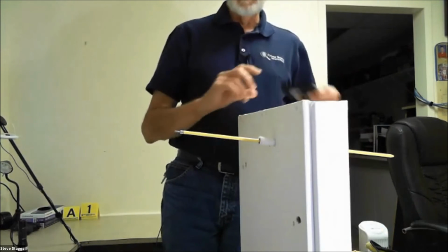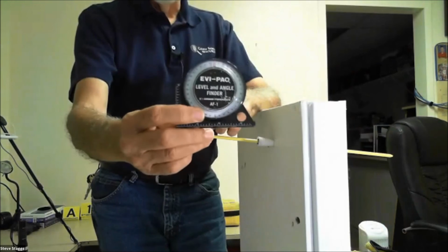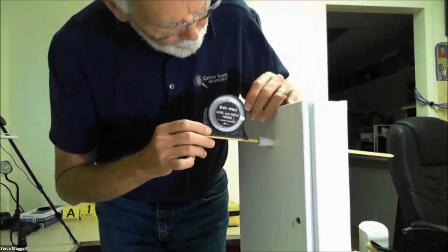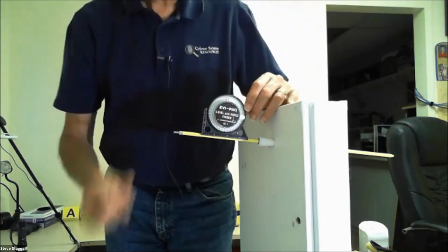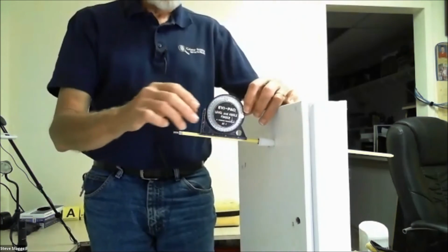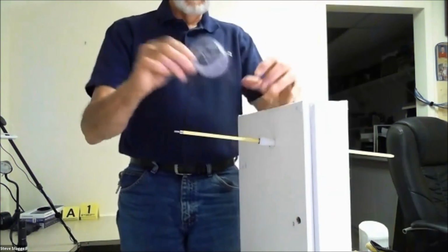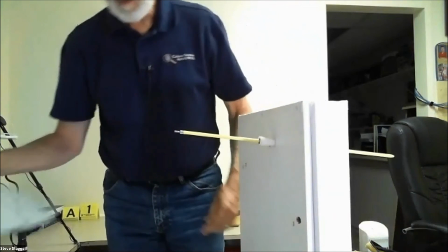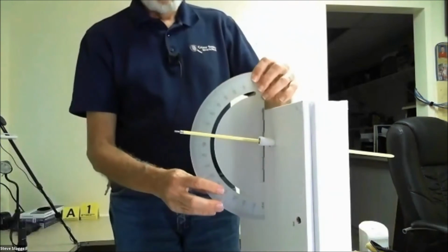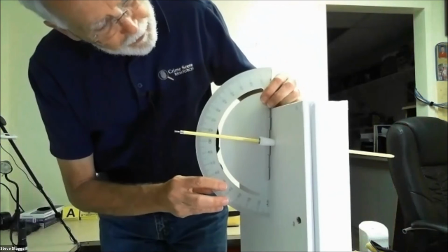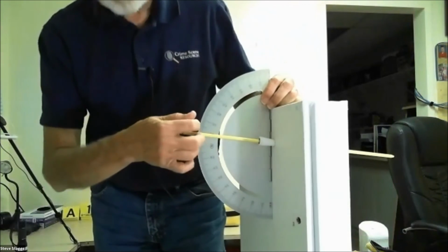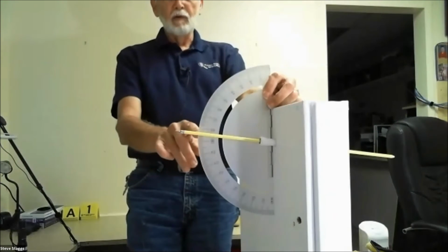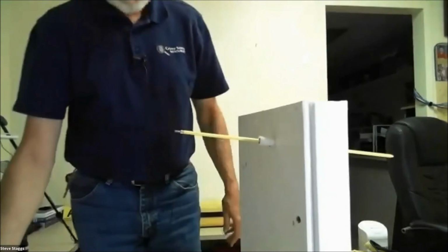What we need to do is some measurements. So one of the things would be to use the angle finder. You just go ahead and set this on here and wait for the needle to stop moving, and you see what angle in degrees our rod is at. Now another way you could do that is to use the protractor. For that, you would have to center this and then go ahead and read the angle. I can read it from this side, and I'd read the angle here. So you could do it that way.